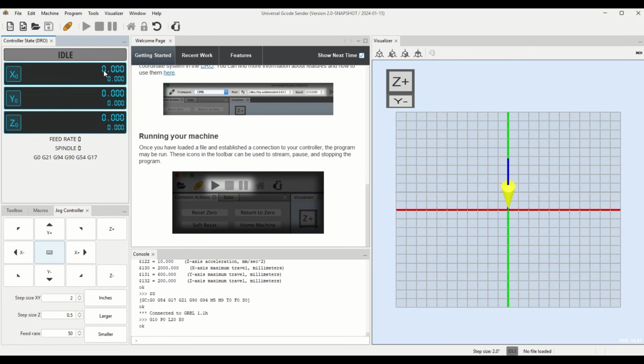The number on top represents the spindle position in relationship to the part you're about to machine, and that's represented over here in this XY axis. So right now it thinks that it is right where it needs to be to start machining whatever part we're going to run. And I'll show you how to change those a little bit later.